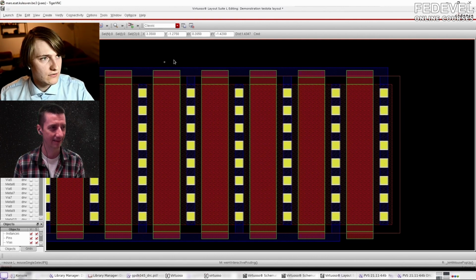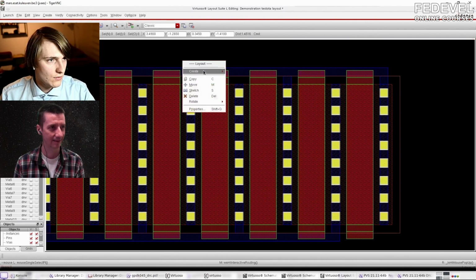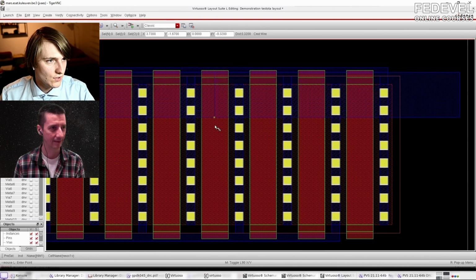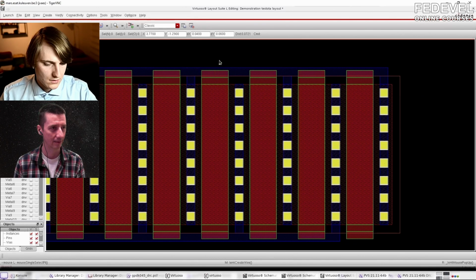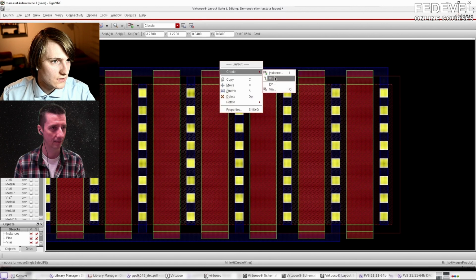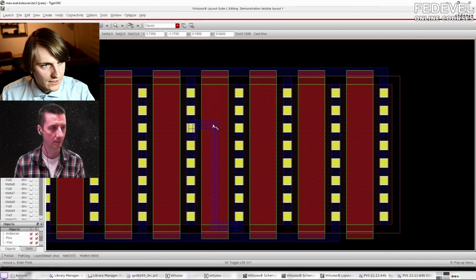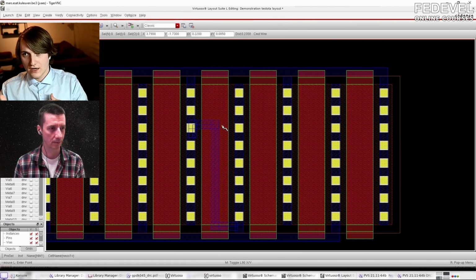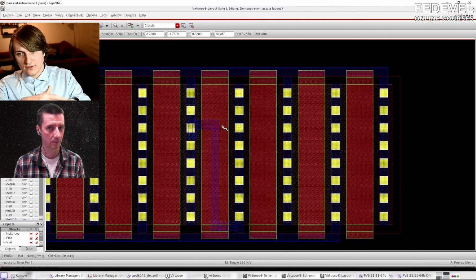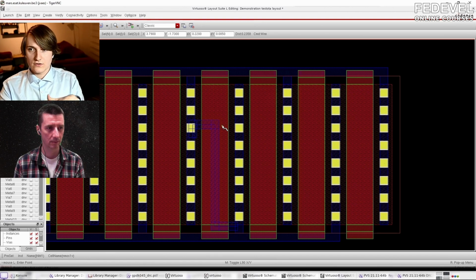The transistor behavior actually changes if I now were to do this. This is a very wide line. Let me try again. So if I start here and I connect this like so, for example, right? Now I place this metal one here in blue on top of my polysilicon. It's not connected, it's just above it. But the fact that it's there results in some strain on this gate, and it will move the transistor parameter. It will shift this a bit.